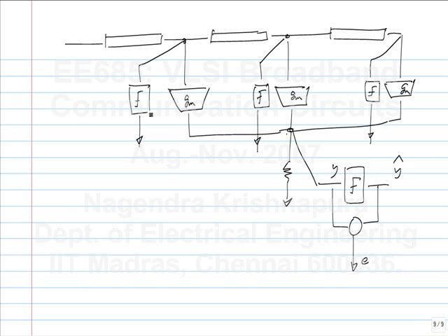Can you do the other method of delaying this? The output of this is digital. Can you delay it using flip-flops and use that as gradients? The problem is that the delay of the transmission line may be nominally equal to one period, but it can vary quite a bit. If it is different from T, then this is not exactly 1T delayed, so this is not a 1T delayed version of this. It will be the sign of this, but it's not 1T later than this one. So you have to use comparators.